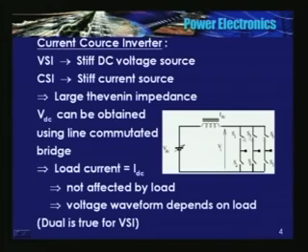You cannot break this current; you have to provide a path by at least one switch in the upper and one switch in the lower being on. In other words, one phase is open.